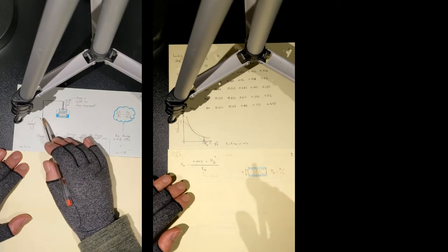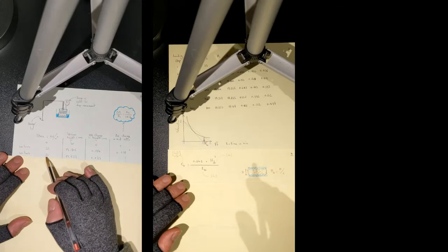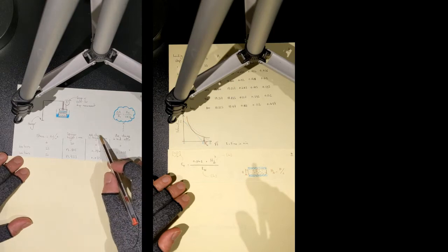So this first phase of loading takes 24 hours. When it's finished, you can top up the load. How? By doubling up the dead weights, and you go up from 25 kPa to 50 kPa. Again, you will keep your soil specimen under 50 kPa for another 24 hours. Then you will measure the delta H, the change in height, during the second step of loading.